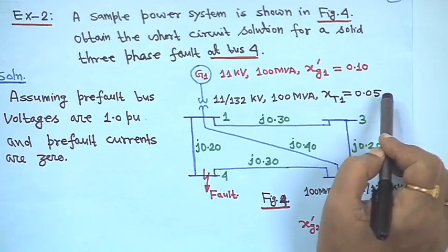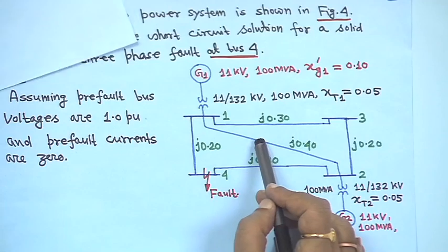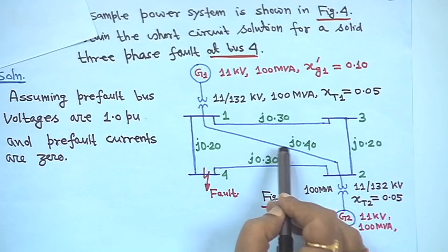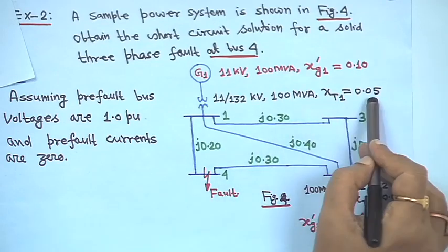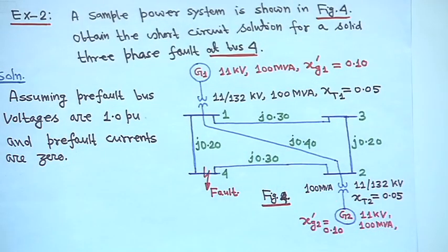After constructing the Y bus matrix, I have this matrix with me, but I am not giving it to you; you construct it, and you will get Z bus equal to Y bus inverse. Now, our interest is to get the Z bus matrix.